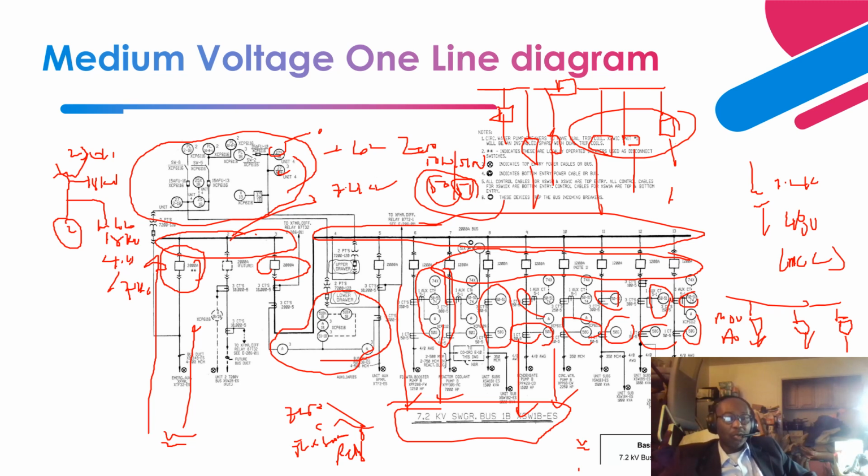Okay. So this is the unit, the incomer that comes to this bus, right? So all these breakers, as you can see, are rated at 1200 amps, and the incomer is rated at 2000 amps. That is a typical standard for how these breakers are rated, right?